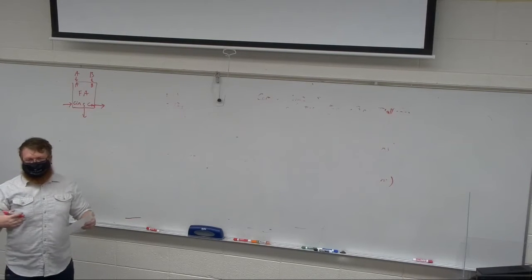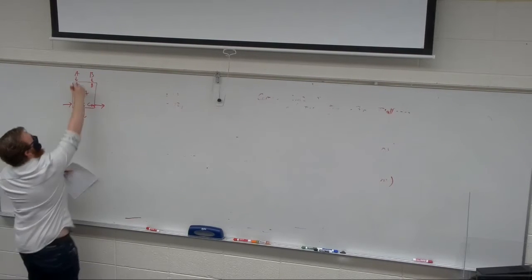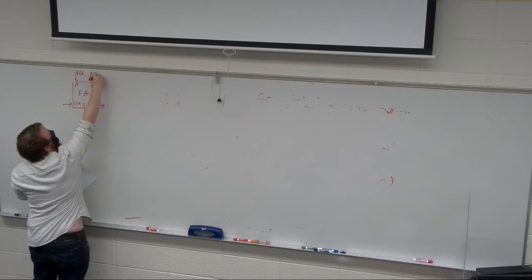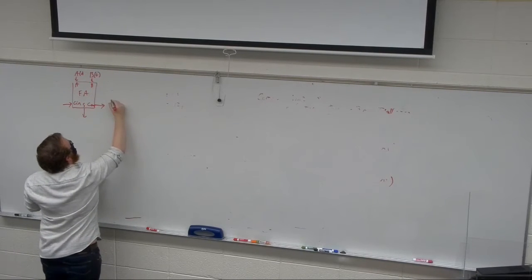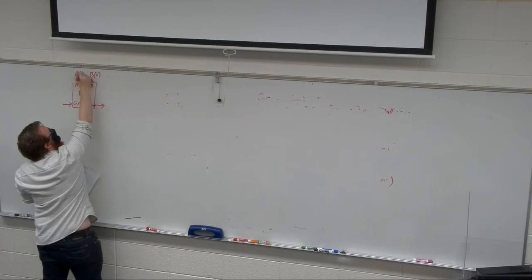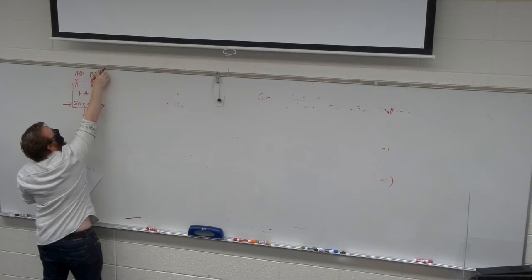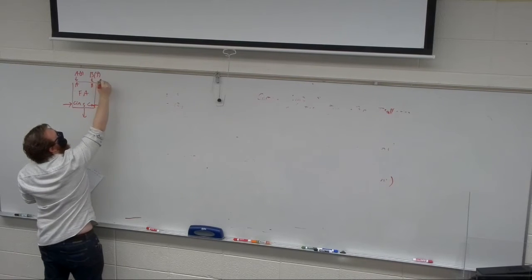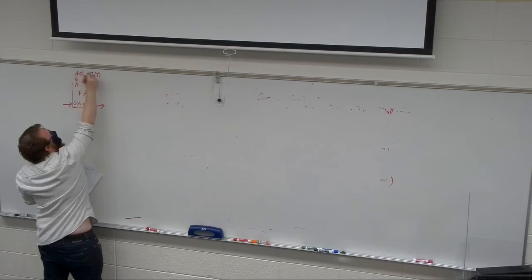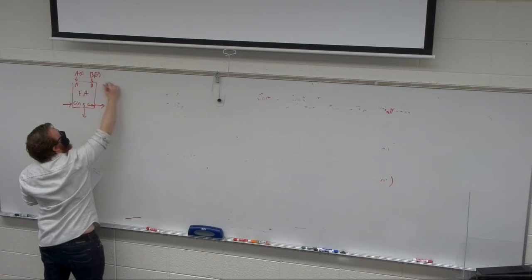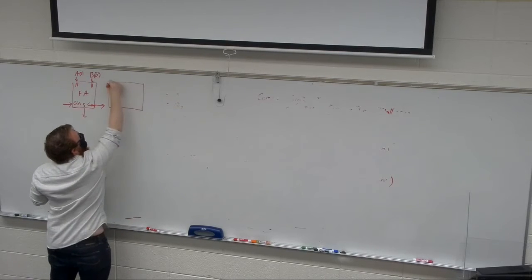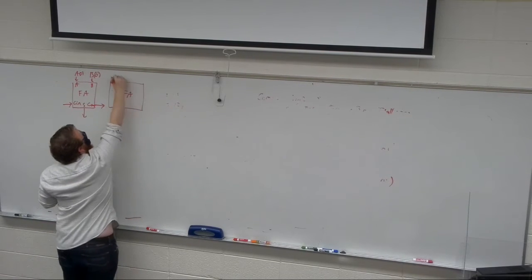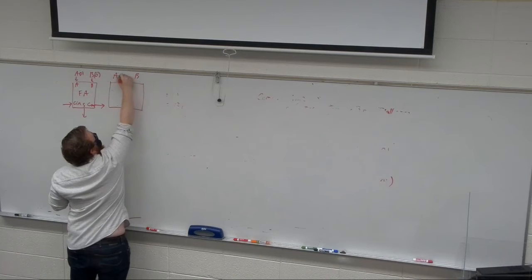And when I want to make this a 2-bit adder, I then say, okay, well, this is A at 0, B at 0. Well, that's not quite right, is it? Let's say it's going to be a 4-bit adder. 3. Nope, it's at 0. Just getting ahead of myself. I take another full adder. It has A's and B's.